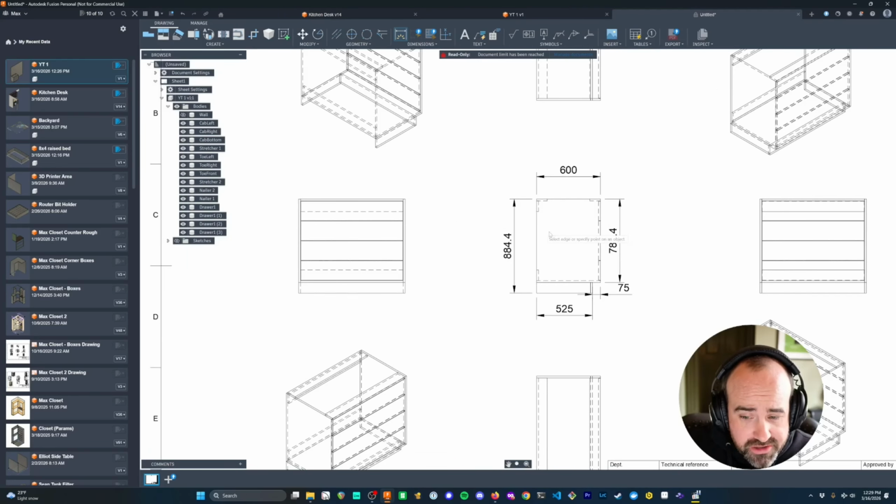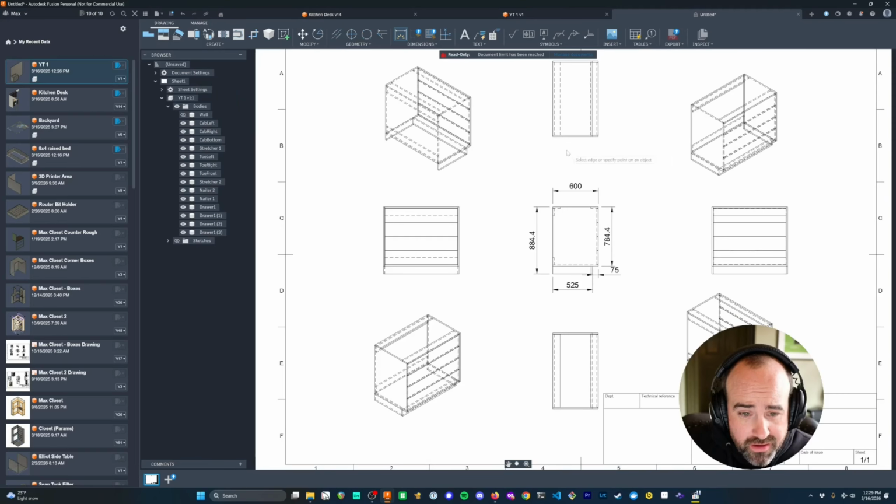I can do dimensions on the other views, but I can't do them on projected views. See, it's not letting me do a dimension here. Well, it sort of did, but I don't know how that works. Can you only do them on side and front? Not these, they call it isometric projected views. You can only do them on orthogonal drawing views, which are the front on, side on. And so whatever's helpful, I can do and draw these dimensions.